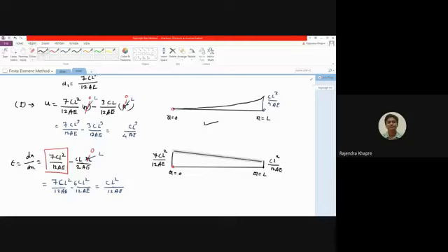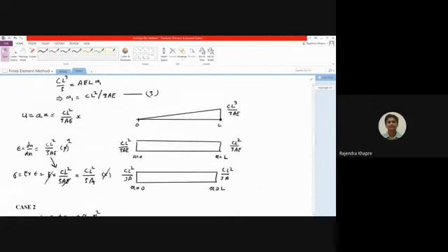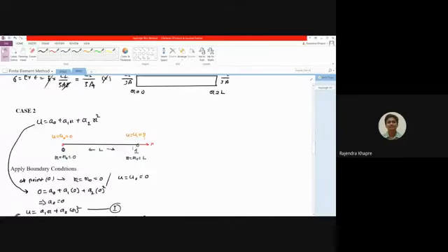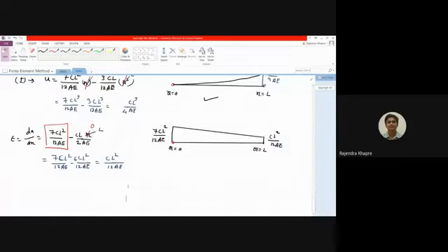You can see that as the x value is changing, your strain is reducing. The maximum strain is there at the support, and as you move towards the end of the beam you are going to get lesser strain. This was not there in the earlier case. If you refer to the earlier case, your strain was constant, and that should not be constant, it should be continuously changing. So now we are getting the correct variation of strain when we take the different polynomial.